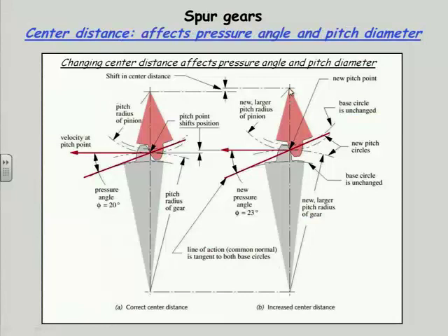As you, I think, are beginning to appreciate, you can't make anything perfectly. There's always going to be some tolerance due to manufacturing errors and assembly errors, so that even though I theoretically wish to have a certain center distance to make these two gears run properly together and have their contact point on the line of centers be right at the pitch circle, I may have some error in the center distance. Maybe the holes were drilled improperly. And that, in my example here, pulls the pinion out of the gear, and that affects my loading.